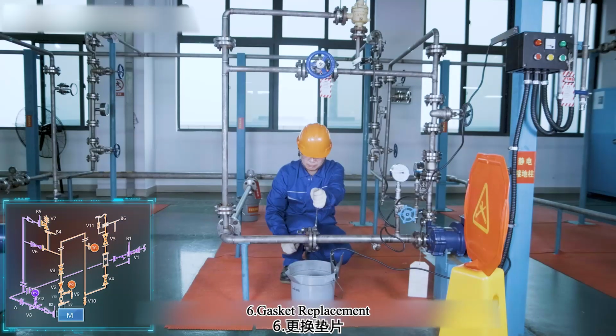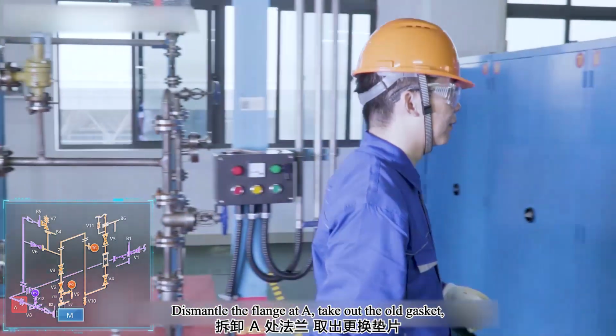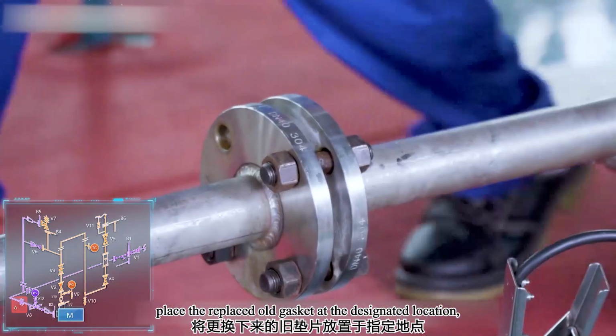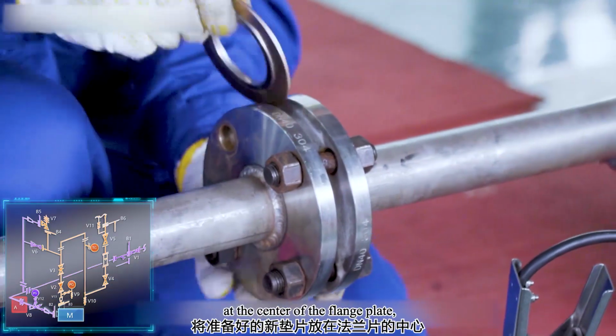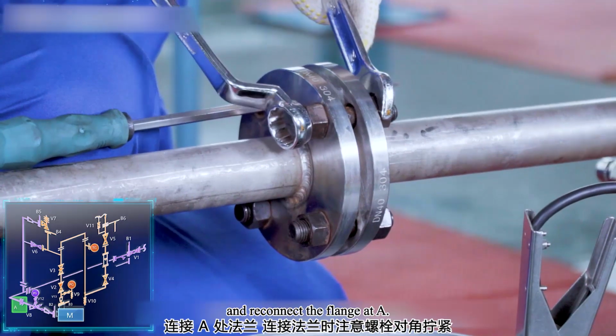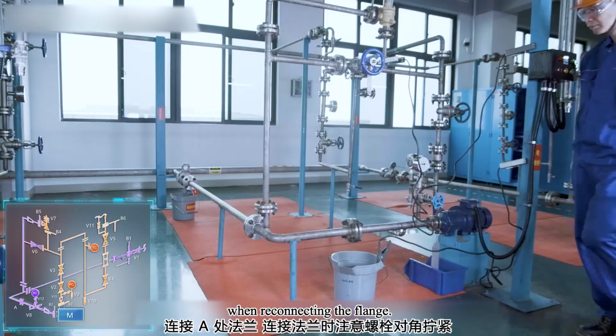Sixth, gasket replacement. Dismantle the flange at A. Take out the old gasket. Place the replaced old gasket at the designated location. Position the prepared new gasket at the center of the flange plate, and reconnect the flange at A. Ensure bolts are tightened diagonally when reconnecting the flange.